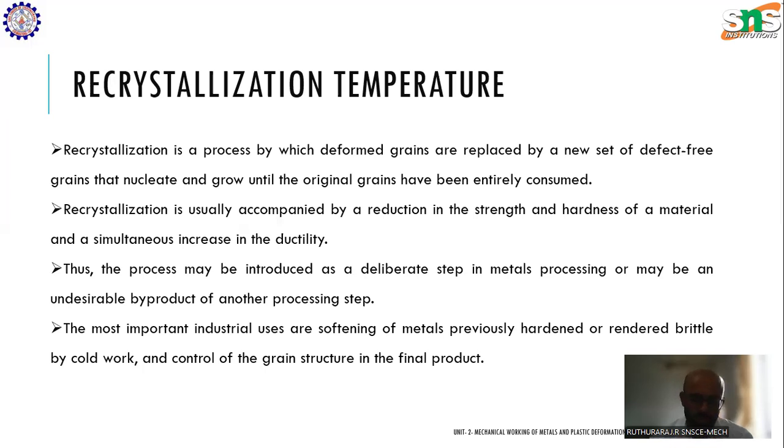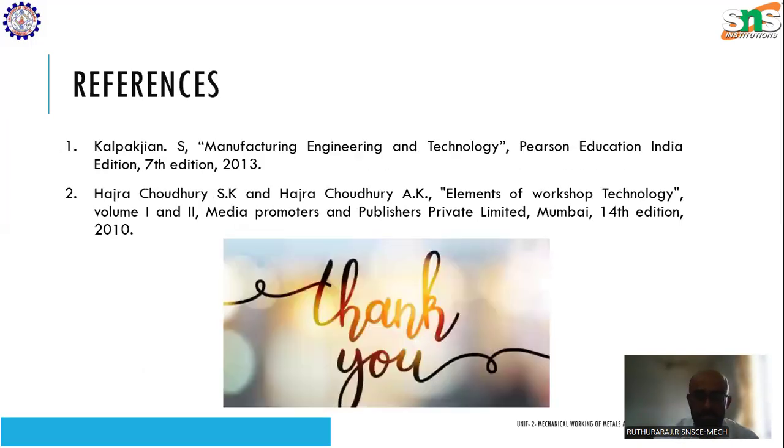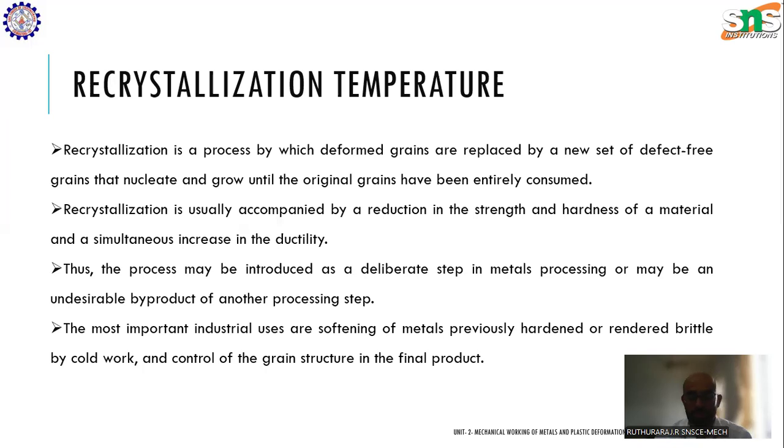You have studied in physics about the cubic nature, face-centered cubic, FCC, BCC, and those crystal structures. From that you can understand that atoms are available in clusters, and those clusters of atoms are called grains. If you look at a part manufactured using the casting process under the microscope, the grains will be larger in structure. I'll show the diagram in the next video. They will be larger in nature.